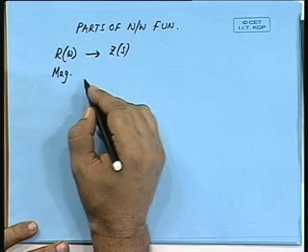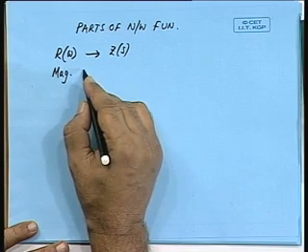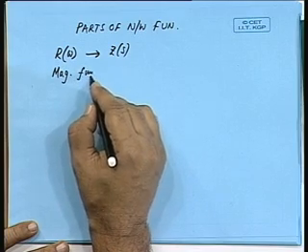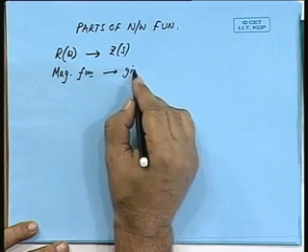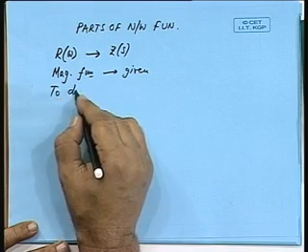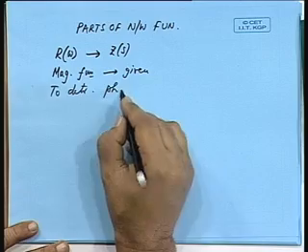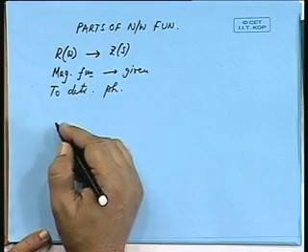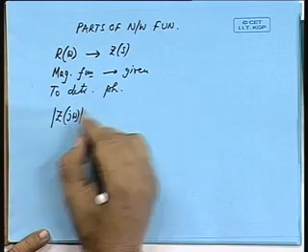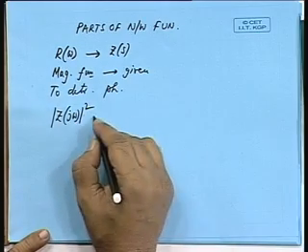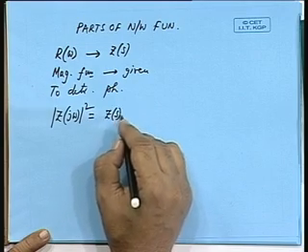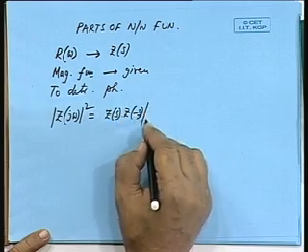Now, today we shall be discussing the magnitude function. If the magnitude function is given, how to determine the phase. Now, the magnitude |Z| squared can be written as Z(S) into Z(minus S) at S equal to j omega.